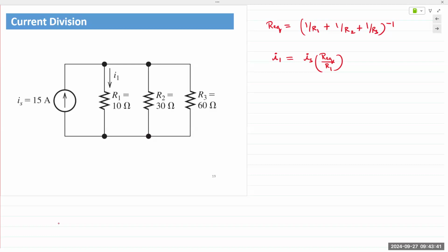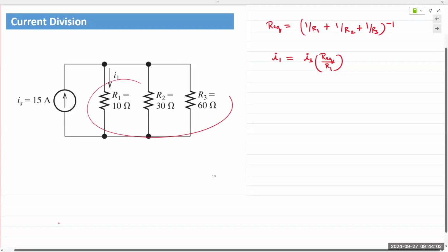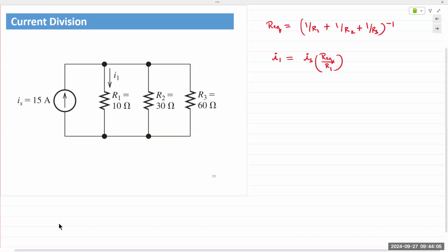One thing I'd like to point out, and this is just a little bit of a tangent. Series connection of resistors, you simply add up. If this was series, it would be 10 plus 30 plus 60, resulting in 100. We don't pay attention because human brains automatically recognize 100 is larger than any of these three resistors. Because we know automatically that if you add something to another quantity, the result will be larger. Am I making sense so far? 100 is larger than 10, 30, or 60.